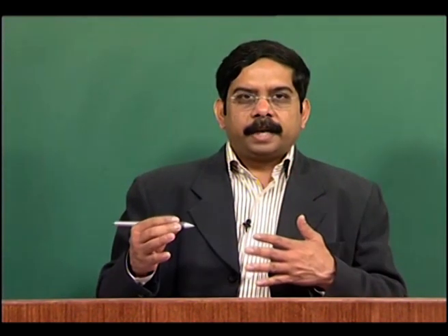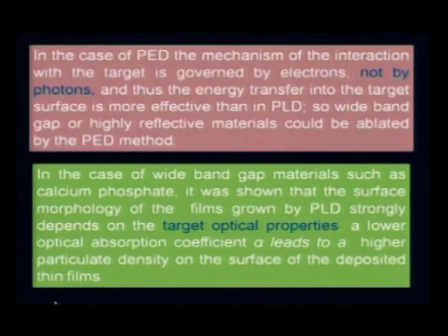PED, because of the energetics that is involved, it seems to have an edge over the PLD process. In the case of PED, the mechanism of interaction with the target is governed by electrons and not by photons, which is the main difference, and thus the energy transfer to the target material is much more effective in a PED process compared to PLD.